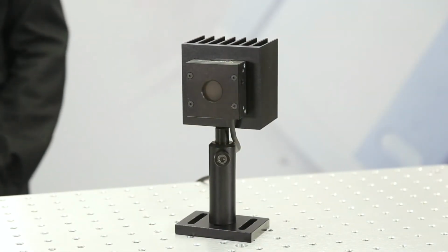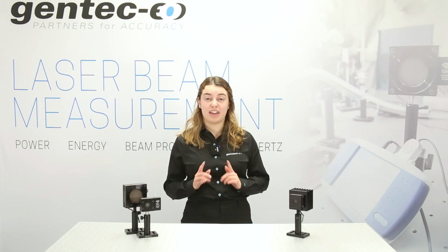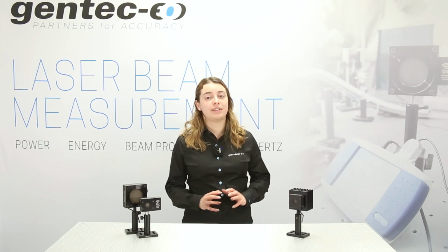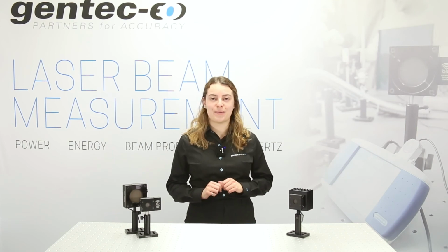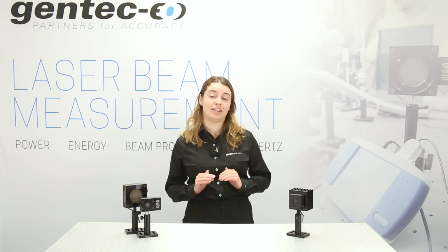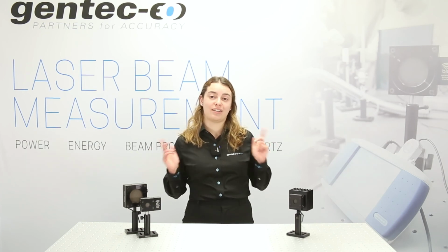Lastly, why is 50% of the area the ideal beam size? The answer is simple. It is the same conditions that we use here at Gentec-EO for calibration. Covering 50% of the active area will assure you that the total power of your beam is absorbed by the detector and that any spatial nonlinearities, if present, are cancelled.